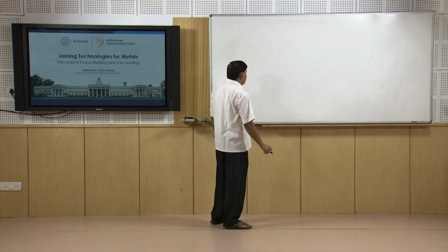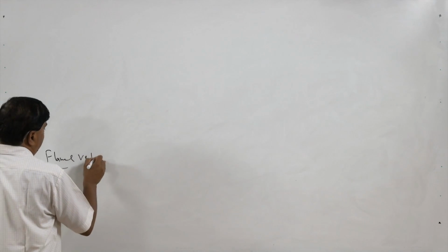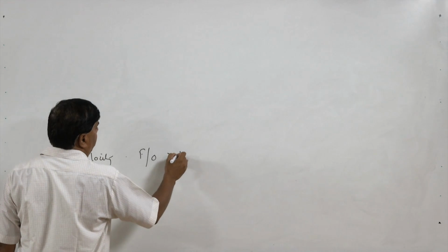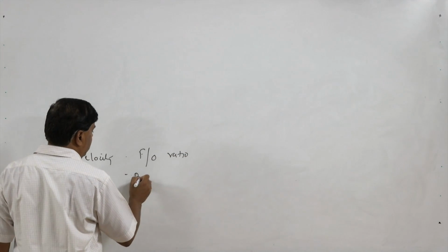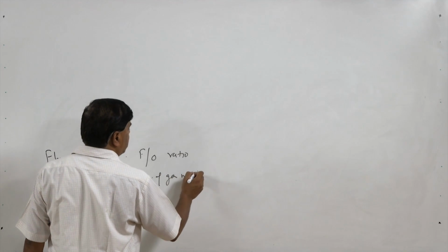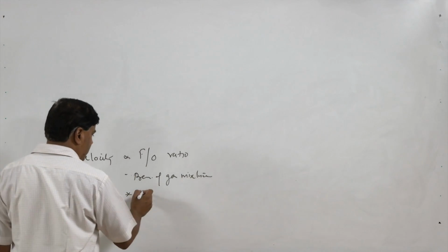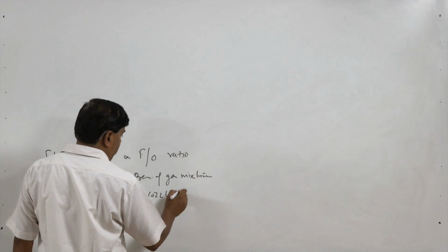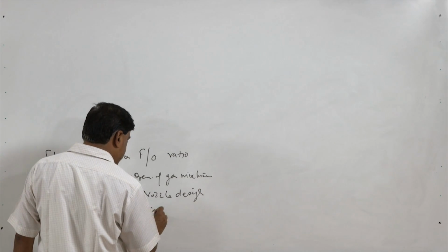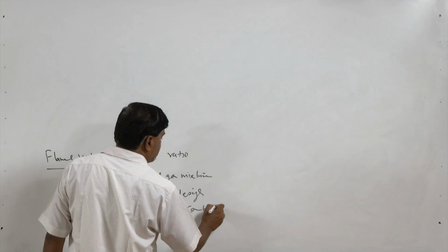Now, the flame velocity depends upon the fuel and oxygen ratio, the pressure of the gas mixture being used for combustion, the nozzle design, and how effectively complete combustion is taking place.